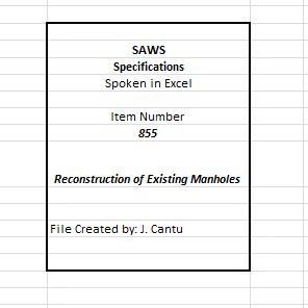855.3 Submittals. Contractor shall submit manufacturer's product data, instructions, recommendations, shop drawings, and certifications. All submittals shall be in accordance with engineer's requirements and shall be approved by the engineer prior to delivery. 1. Submit proposed methods, equipment, materials, and sequence of operations for sewer construction. 2. Plan operations so as to minimize disruption of utilities to occupied facilities or adjacent property. 3. Submit all test reports and pre- and post-sewer television inspection video. 4. Videos become property of SAWS.